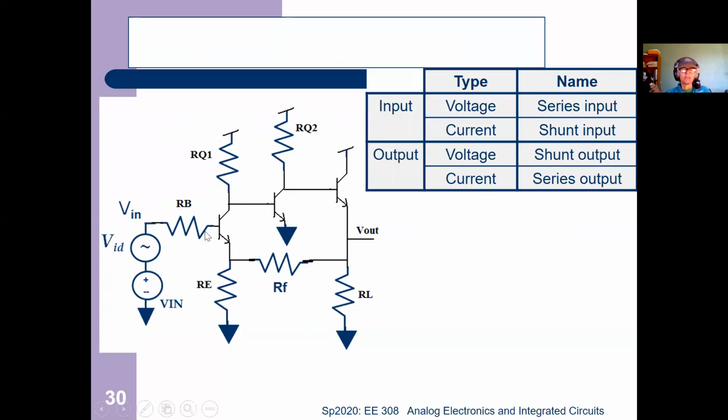Okay. All right. So the way you find AV is you circle all the vanilla amplifiers. And again, that's my word, and nobody else will understand it, but it's the most basic version of the amplifier. So it's a common emitter with a passive load or common emitter with an active load. It doesn't include degeneration or cascoding. Well, I guess if it was cascoded, the cascoded transistor would be considered a transistor. So it's just not with degeneration. That's the easiest way to say it.